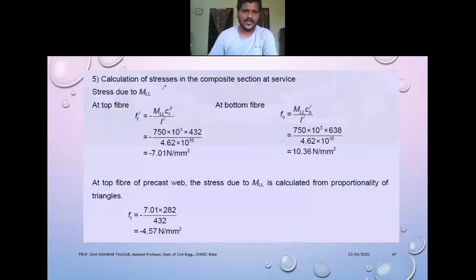Then we need to calculate the stresses in the composite section at service. Now it is behaving as a composite section. We need to calculate stresses at service, and here we need to consider the stress due to the live load moment.